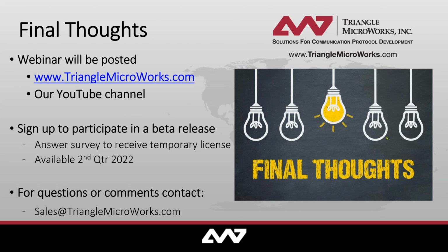So what you could easily envision is developing an action that takes multiple breakers in on the input side, and sets up the required conditions. Then if you run this action, it will look at all those source breakers and then watch the target breaker, the one that you're actually testing at the particular time, to make sure that it does the appropriate thing, either operates or not, depending on whether interlocking is satisfied.